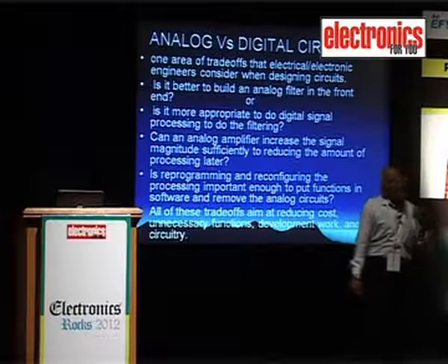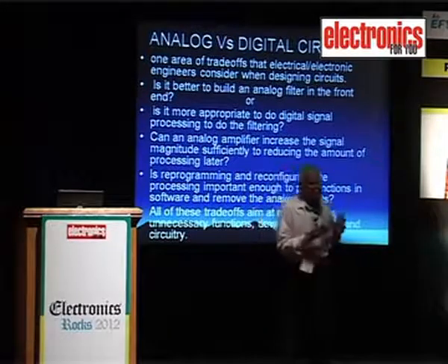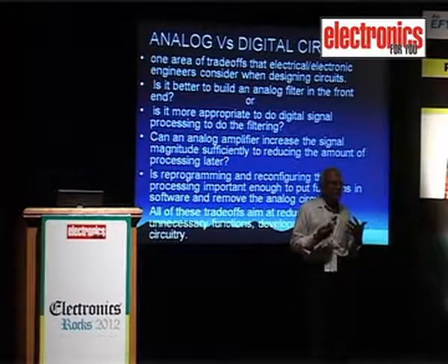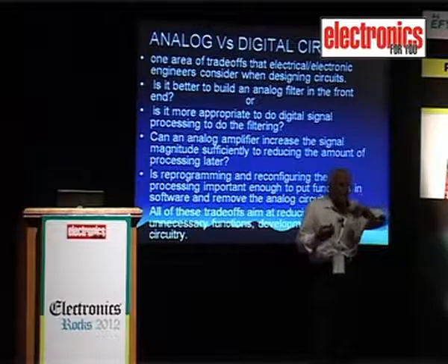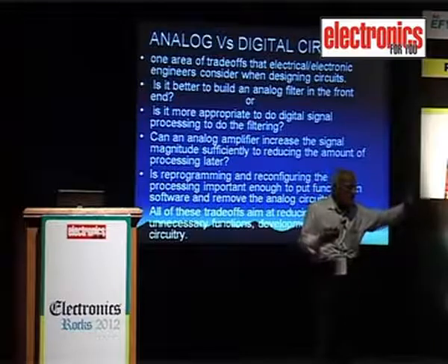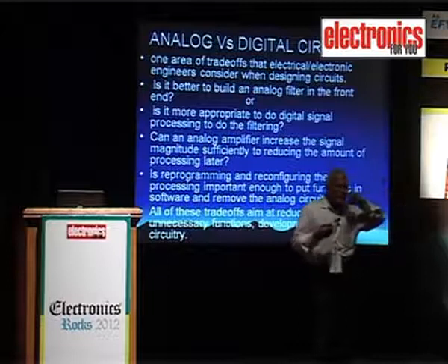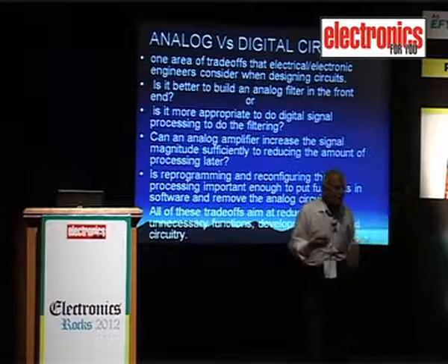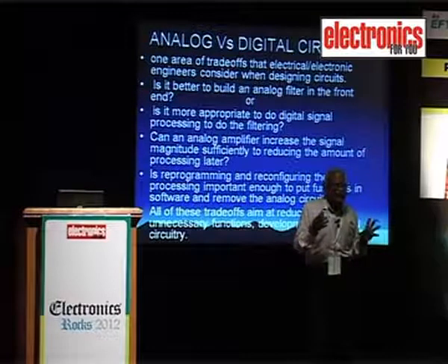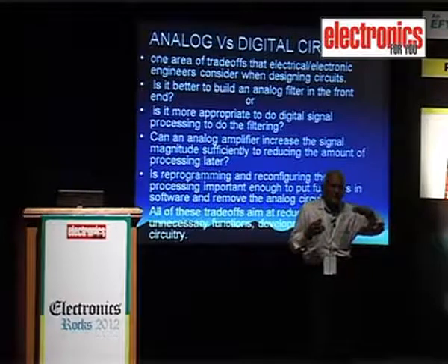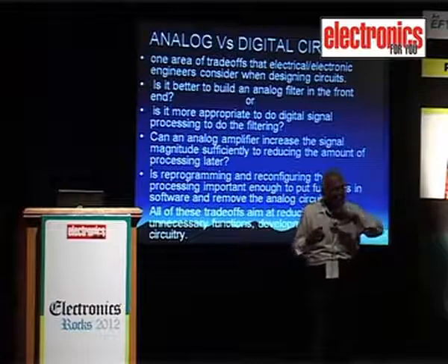And when you put the battery on boost charge, and at the end of the week the battery is getting discharged, the battery has come down to 49, 48, 47. You no longer can use your system otherwise, because most of the telecommunication systems which use the same 48 volt DC power supply, be it cellular radio or other electronic equipment for communication, they all work on a 24 cell battery, which is 48 volts, typically mentioned as 48. The normal charged voltage is 51.2. The moment you remove the battery charger, it will go down to 49.